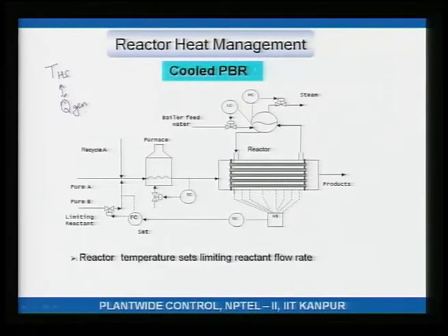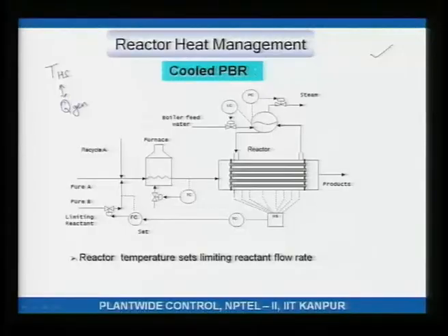First scheme, this is doable in practice. Scheme 2, which we saw just before this, where you were adjusting T in, that is not recommended in practice. There was also the other scheme that we discussed first, where you are adjusting the pressure set point to hold the hotspot temperature constant. This is also done in practice. When would you recommend this? Well, conventionally the most commonsensical way of controlling the hotspot temperature is to adjust the amount of heat that is getting removed.